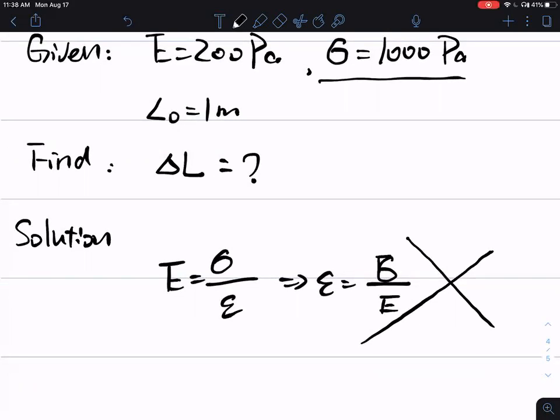But that's something I think a lot of students make mistakes on. The Young's modulus is given for most of the materials. So when they get a stress, the load they apply to the material, they just look up online, find the Young's modulus, and find what is the deformation strain caused by that stress. And it turns out they didn't consider if that stress is under elastic deformation or plastic deformation. And it is very important. I want you to keep that in mind. It's a very important thing.